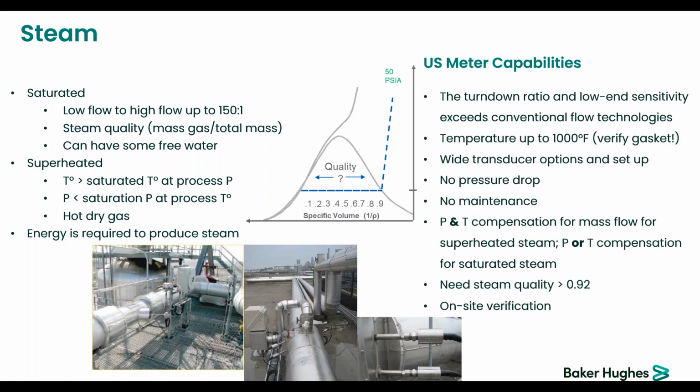Okay, so you have some photos there. The first one on the bottom left is the saturated one. You can see the line is insulated. Steam lines are typically insulated because you don't want the temperature to drop and increase the condensate content. The two other pictures are from the same line. This one is just above the saturation point, and this is a boiler system from one plant producing steam for feeding the plant next to it.